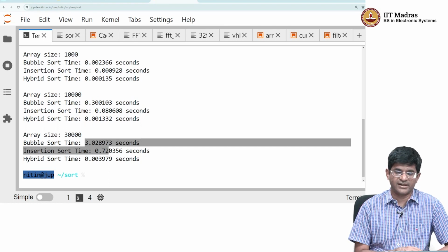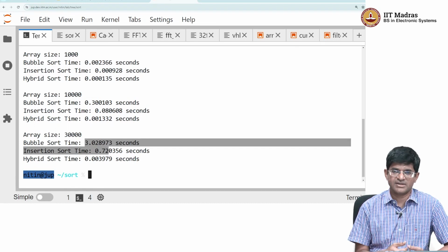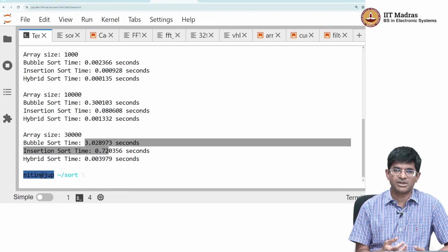One more related aspect is that if I have an algorithm that runs very fast, it is possible that during the time that it runs fast, it actually consumes a lot of power, maybe because the instructions it uses are somehow activating more memory blocks. But the point is, it does its work very quickly, and then you can put your CPU into deep sleep, perhaps. It might very well be that such a scenario ends up consuming less energy in the long run than something which takes lower power but takes a much longer time to run, right.